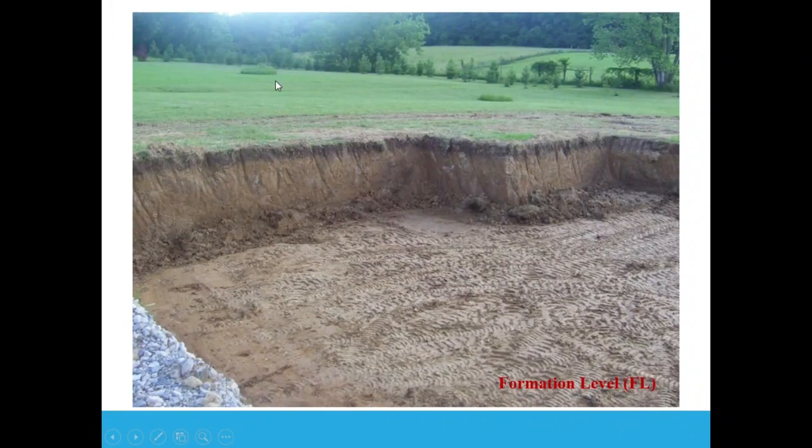Okay, so let's say that you have an area and then it should be excavated to a specific formation level, for a basement for example. So here is the ground level, and then you would like to excavate to a formation level. So this is the height of the excavation, or the depth of the excavation. So we are going to excavate to a formation level, which is the reduced level of the ground here down.